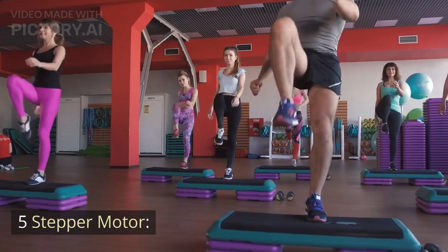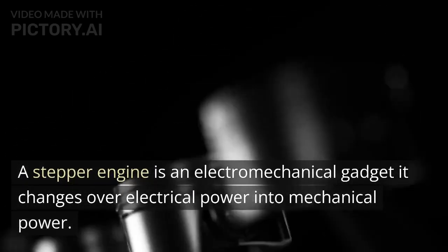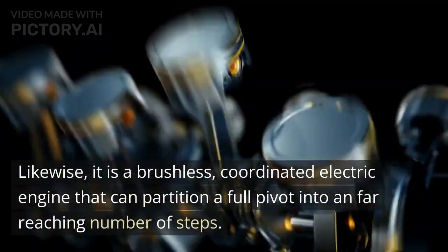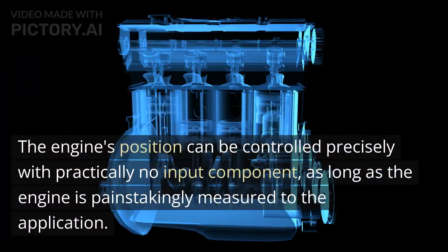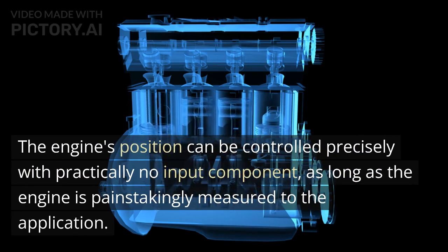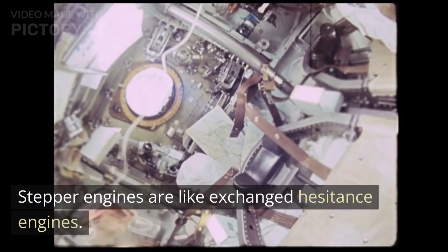5. Stepper motor. A stepper motor is an electromechanical device. It converts electrical power into mechanical power. Also, it is a brushless, synchronous electric motor that can divide a full rotation into a large number of steps. The motor's position can be controlled precisely without any feedback mechanism, as long as the motor is carefully sized to the application. Stepper motors are similar to switched reluctance motors.